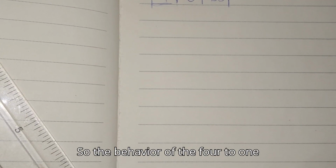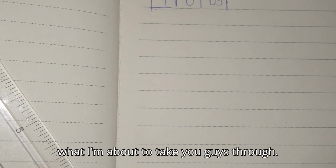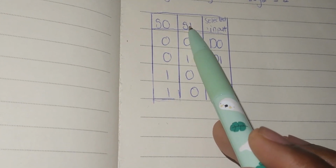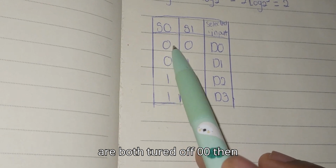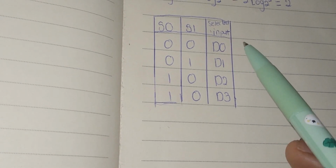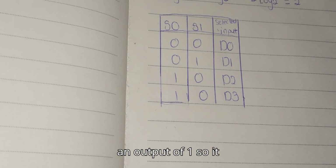So the behavior of the 4 to 1 multiplexer can be precisely described using a Boolean expression, and it's what I'm about to take you through. When the binary values of the select lines S0 and S1 are both 0, that is 0, 0, then it means the selected input D0 is passed to the output.